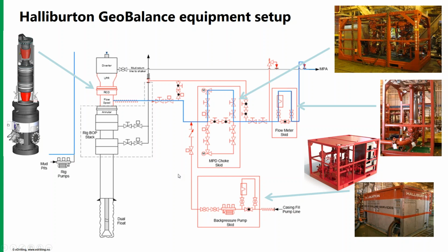That means you'll be able to keep the choke within an optimum range, so that you can control the pressure accurately. Instead of a back pressure pump, you can use a rig pump diverter, which gets the flow from the rig pumps from the stand pipe. Then you will not need a pump in addition.